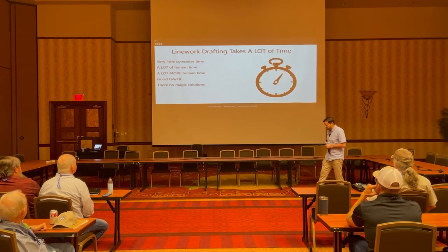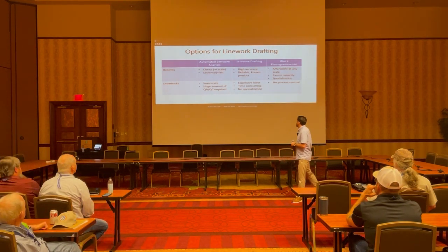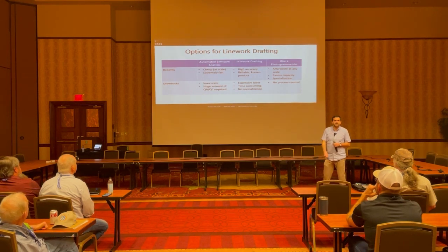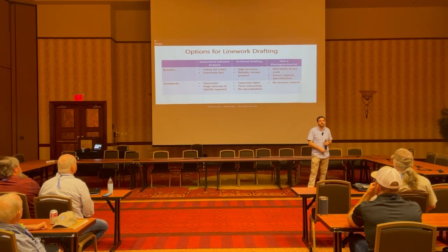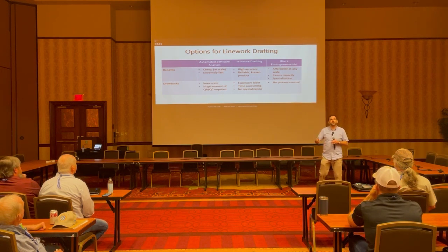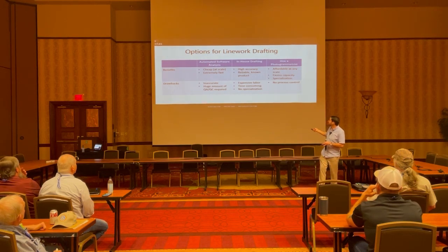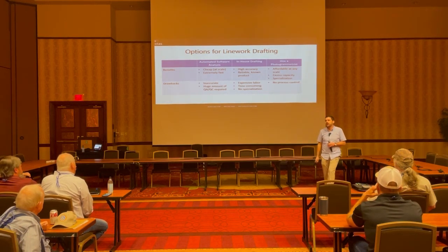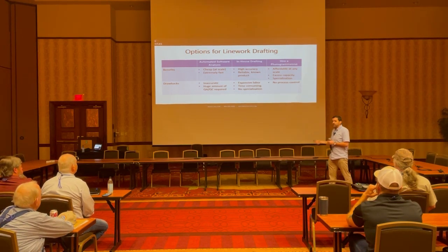Like I mentioned, there is no magic solution though. Like photogrammetry, there are also different options for how you do this. There's automated software analysis that can automatically pick up curb lines and break lines and all kinds of different things, or power poles or manholes. And those are getting a lot better, but right now they require an enormous amount of QA, QC, and typically aren't quite there. Sometimes, some applications they are. Again, this is another one of those places that's a really, really rapidly advancing field, which is really exciting to kind of monitor.